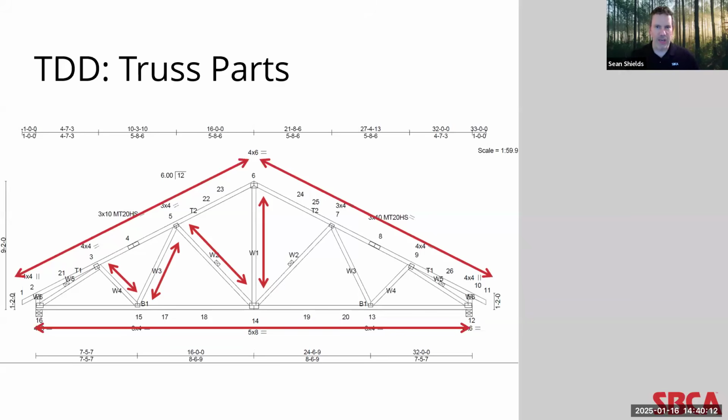And again, I mentioned this early on, the truss designer and component manufacturer has a great deal of latitude in determining how these webs are spaced throughout the inside perimeter of the truss. And that really is the magic of the truss itself. Again, putting these members into compression and tension to adequately transfer load from the peak of the truss down through the exterior bearings.